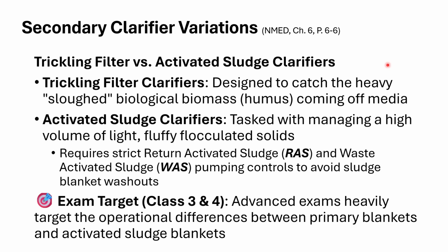In a secondary clarifier, what we're doing is we are also adding in activated sludge or microbes that, and we'll discuss this in the activated sludge chapter, we've basically given them some oxygen. We've given them a surplus of oxygen, and we've made them very hungry to go metabolize that waste, the organics in that waste. So the secondary clarifier is a biologically driven process, okay? And we can have a couple of different ways of approaching this biological process.